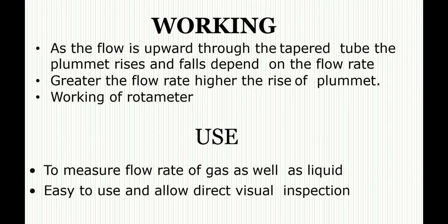So what are the uses of rotameter? Basically rotameters are extensively used in the chemical industry, such as bulk drug. In fermenters, the supply of air is controlled through a rotameter only. Rotameters are satisfactory both for gases and for liquids at high and low pressure.